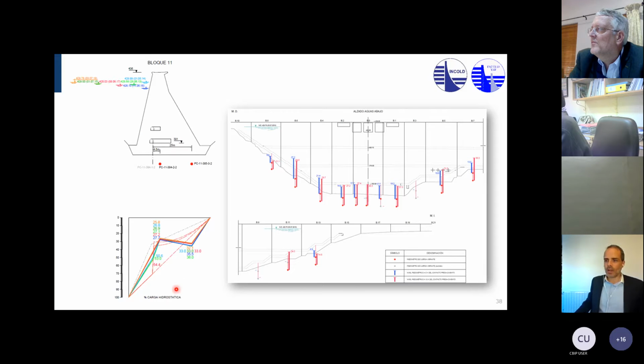And if we represent this slope, you can see that it's not linear. It's not really following the typical linear. And this is a trend that we find in real dams, that the uplift pressure law is not linear, and when it gets to the drainage gallery, you always have a break in the lines. Then this is kind of parabolic. So it's linear here, then when you get to the gallery, it builds up until you get to the downstream toe, and this is a parabolic law, and up to this point, well, we consider it to be linear.